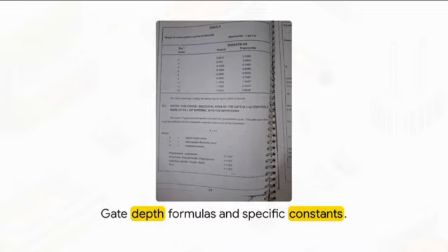All right, Section 3, perfecting gate design, getting the plastic in efficiently. So we know how to hold the mold together, and we know how to push the part out, but how do we actually get the plastic in there efficiently? Well, the gate is essentially your master control valve. The cross-sectional area of the gate controls the exact rate of fill into the impression. But specifically, I want you to consider the depth. The depth of the gate dictates the time for which the gate remains open. Think about it. If it freezes too fast, the extremities of your part just won't fill. But if it stays open too long, you're just wasting valuable cycle time.